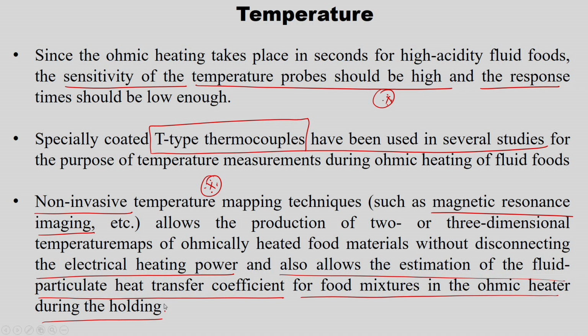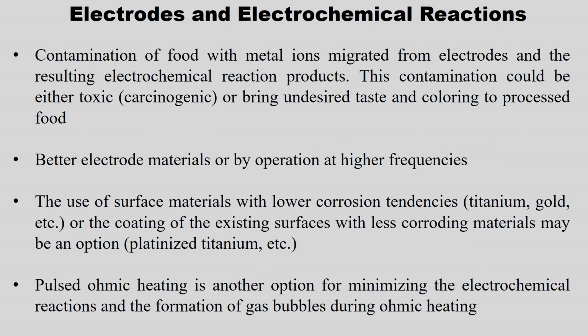So, what they do is they employ a magnetic particle, which is nothing but a tracer particle. This is used as a tracer particle to measure the temperature inside the holding tube. It is sent along with the fluid, and it is further used for temperature measurements. So, this helps me as an alternative to the conventional thermocouple temperature measurement system.